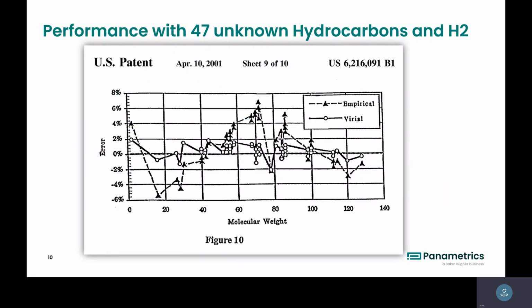Of course, there are some other ways to calculate the molecular weight from sound speed, say empirically. For example, if you assume all the gases are ideal gases, you can calculate the molecular weight from sound speed very easily with a simple ideal gas equation. But of course, your error will be much bigger.